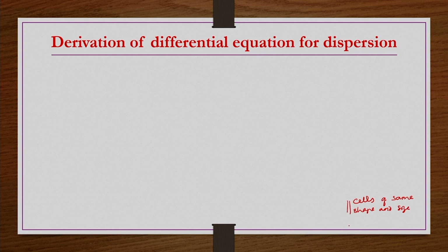Another one is that these cells are porous, because our packed bed is one type of porous media, and interstitial spaces are there. So, the entire bed is not completely packed; some volume fraction is void space. Because of that, we have to take these cells also as porous.